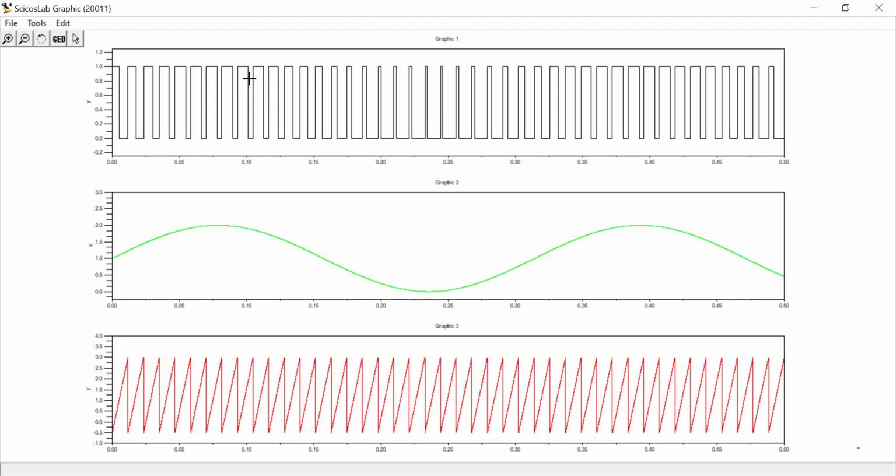I've set this up for about 90% pulse width during the 11.6 milliseconds and about 10% minimum. You adjust the voltage on here to get the plus or minus 90% and 10%. If you make this, let's say, positive voltage less, then this will be a little bit more than 10%. So you can play with the sawtooth to get the absolute settings for the pulse width modulation.